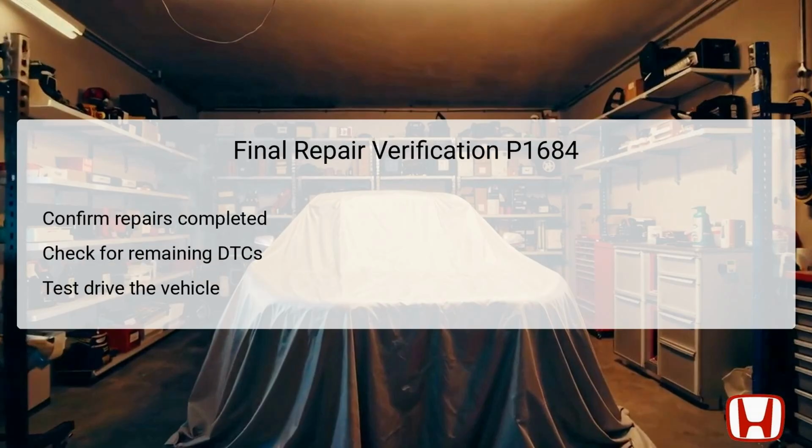Once all diagnostic and repair steps have been completed, it's crucial to verify the integrity of the repairs made regarding code P1684. This includes ensuring that all relevant tasks were performed and the throttle body has been adequately cleaned or replaced. The technician should thereafter check if any remaining diagnostic trouble codes, DTCs, exist in the system.